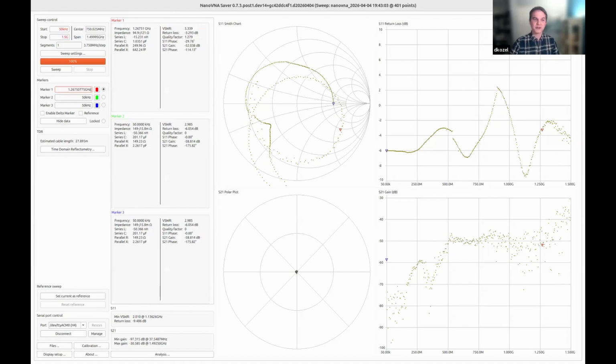Yeah, loss in both directions. We have a reflection, ideally a total reflection, out at that open circuit point. The power is going all the way through the 3 dB attenuator, dropping 3 dB, hitting that open, and reflecting straight back. And it incurs another 3 dB of loss. So that's really useful. That's fun. And we can see we've got 3 dB of loss.